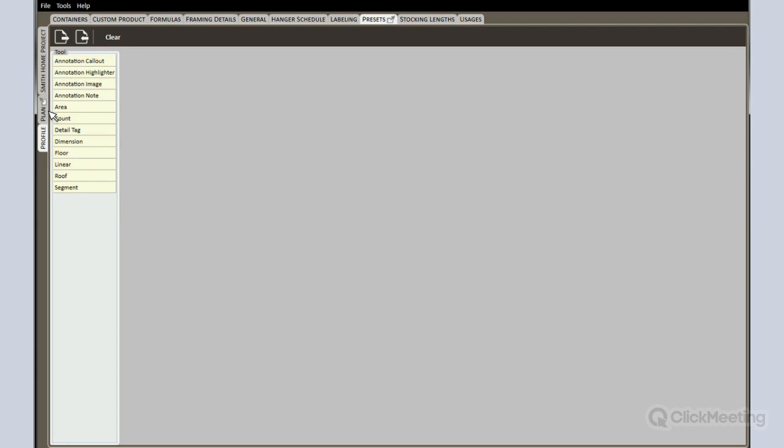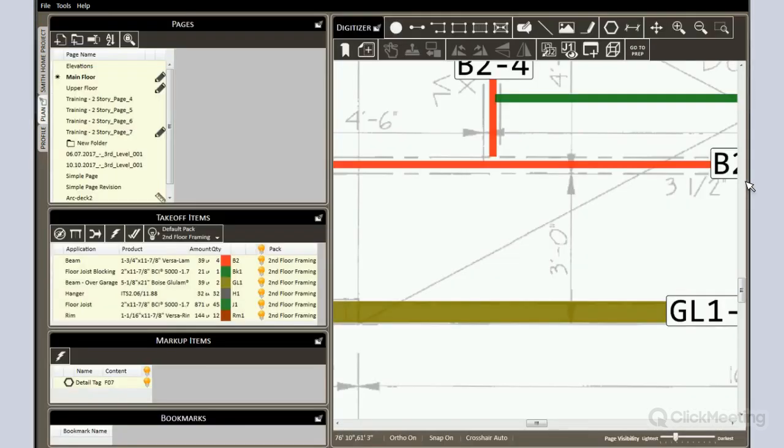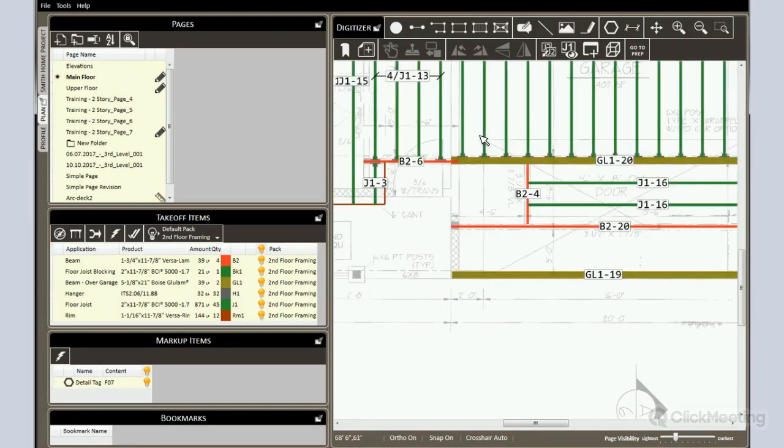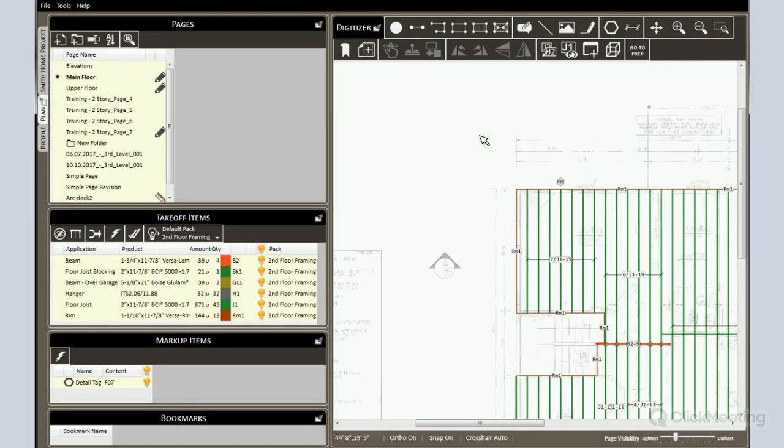Coming over to the plan tab, we have added several different options. To start with, one related to callout lines. Some of you have found a need to draw more callout lines within one operation. Previously, when you drew a callout line, and I'm referring to this tool up here in the toolbar, you would be able to draw one callout line and then the command would end.